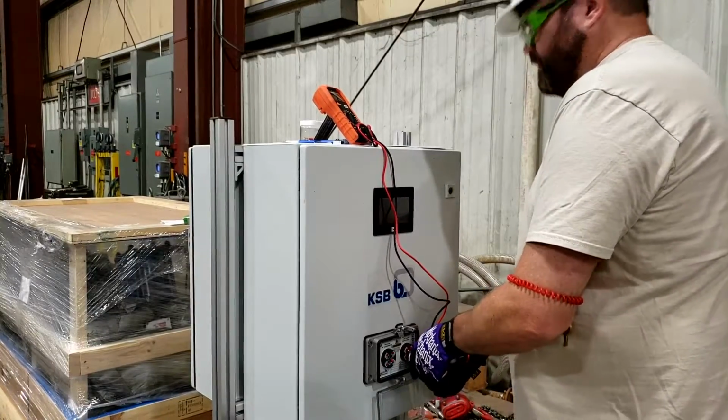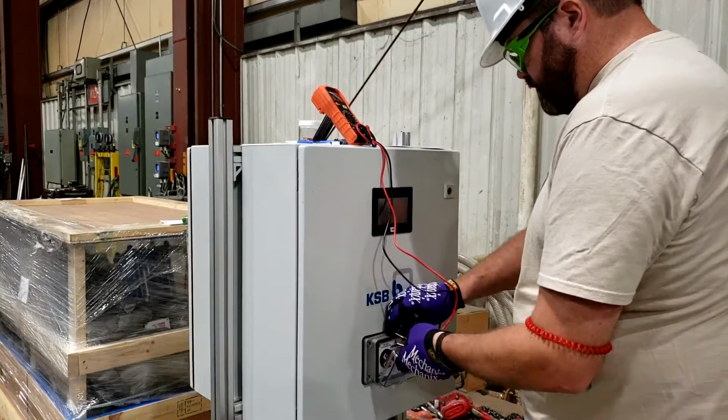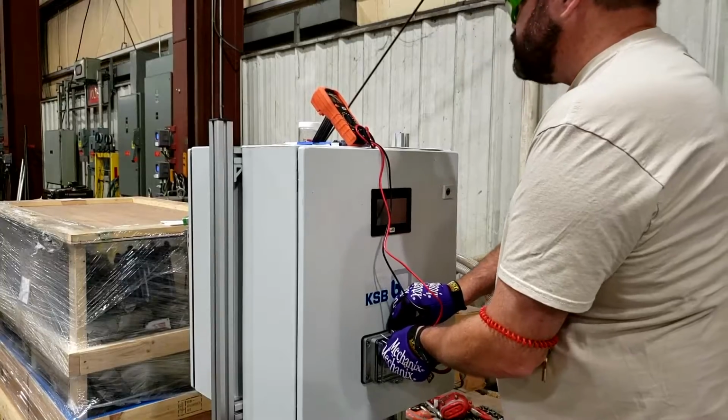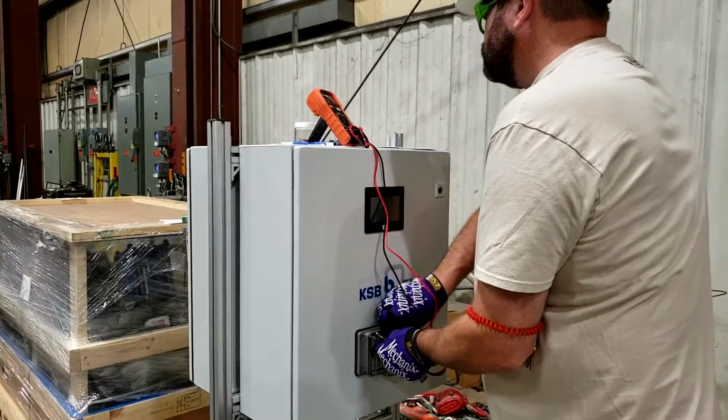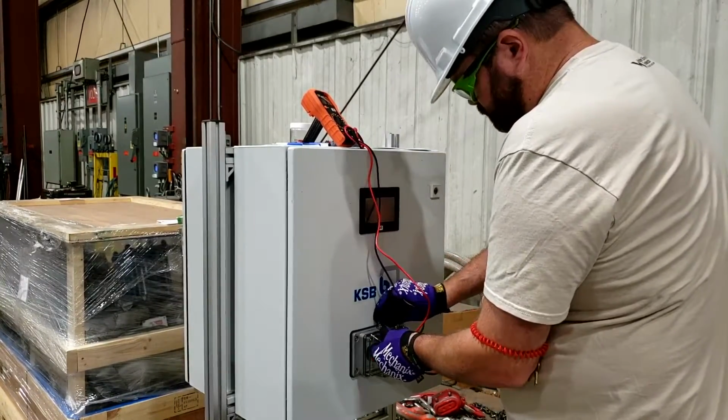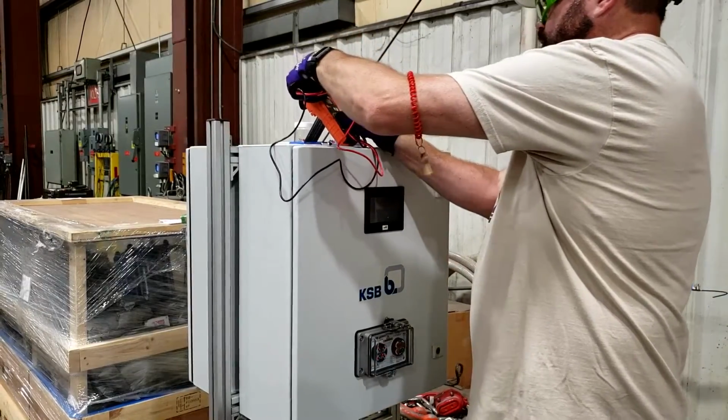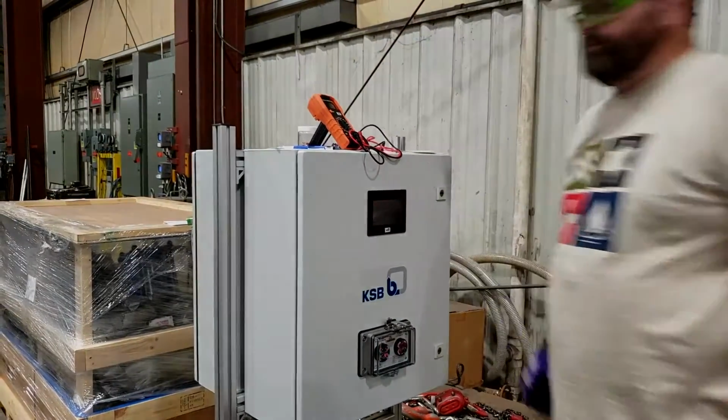After each test, you'll communicate out loud that those particular tests or legs are clear. Once all 6 tests have been completed, close and latch the door to the voltage test station and communicate out loud all voltage is secured and no arc flash danger is present.